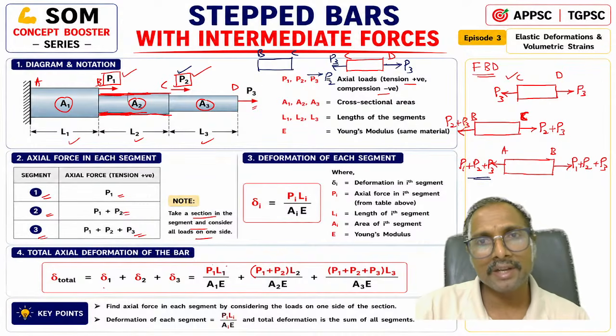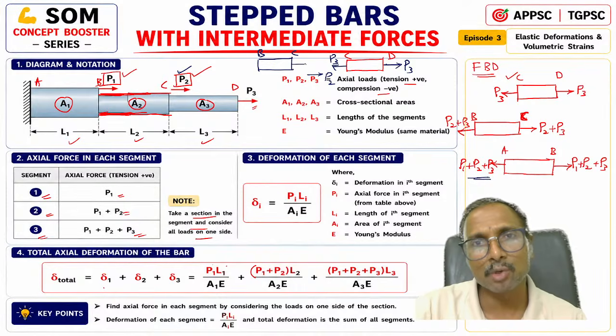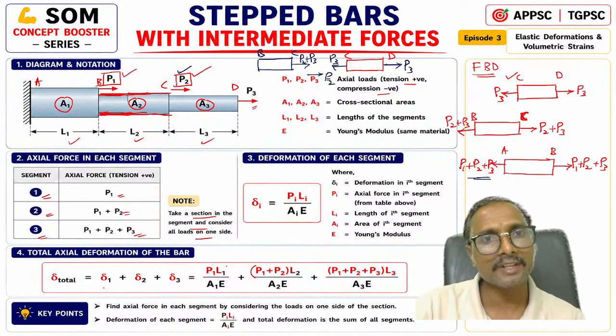Yeah, Mahendra, coming to this. At C point, net load P2 right side is there. So what should be at C? Already here left side P3 is there, so we need to remove it. We don't want P3. So we need to apply P3 on the right side. If we apply left side P3 and right side P3, what happens? It becomes 0. But do we have 0 at C, or is right side P2 there? Right side P2 is there, na? So what should we do? We need to apply this right side force only. P2 we need to add. So right side P2 plus P3, left side P3. What is the net value? P3 will cancel. Only that P2 right side we are left with. Is it matching with this external force applied or not? Yes. Point is in equilibrium.